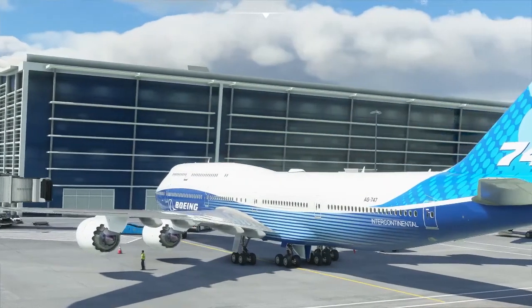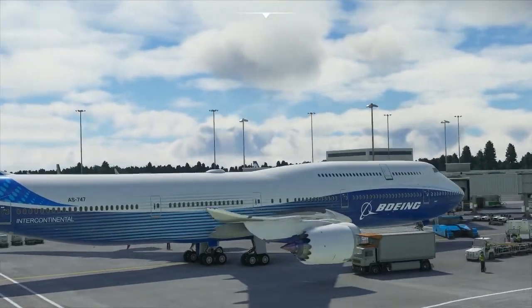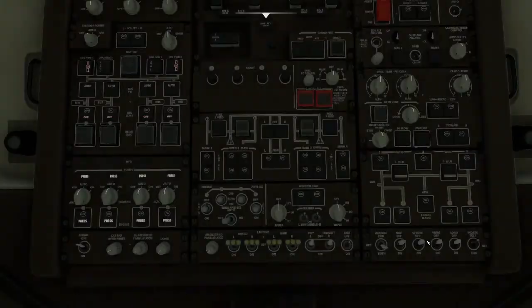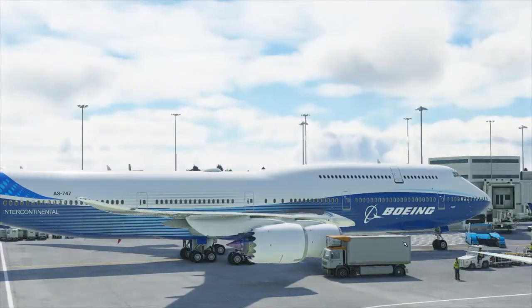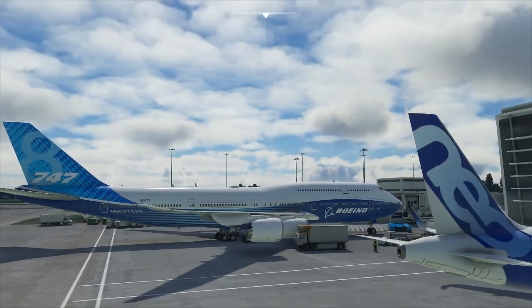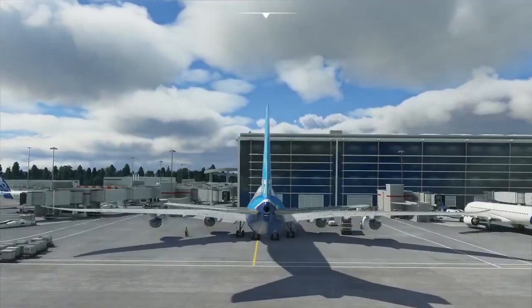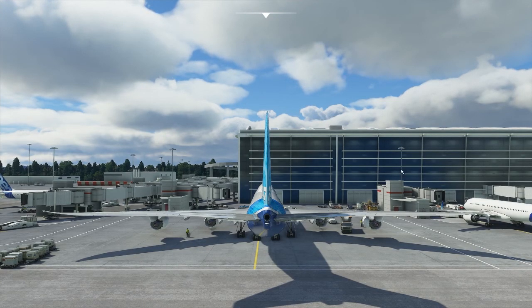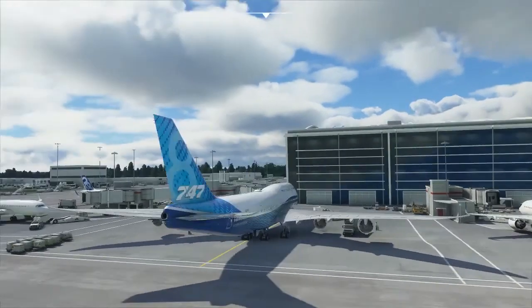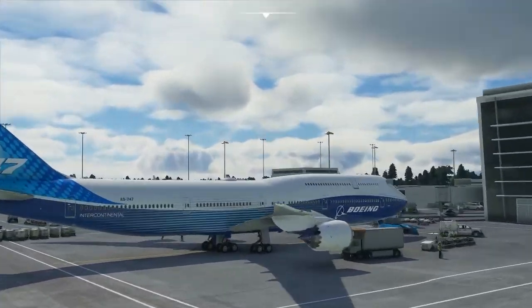I used to say red on your right gives you a fright, and oops, need to turn them on. Red on your right gives you a fright, and the reason for that was if there was a plane flying past your nose here, if you saw the red light, it meant it was pointing towards you because it was on their left wing, so they were going to fly out in front of you. So red on your right gives you a fright. You can thank my ground instructors for that one.